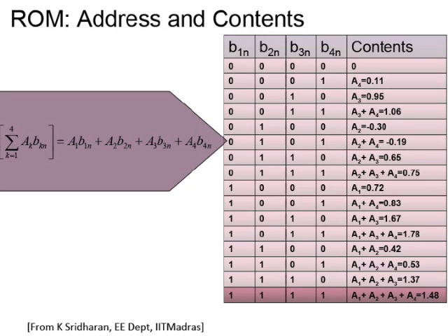So imagine you have two inverters, one connecting to the other, two back-to-back inverters, right? If you put input as 0 on one of them, the output of the first one will be 1, which will again be 0. So each will help the other. That's basically the structure of a memory cell, which is also what you have seen in the case of a latch and a flop, right? Two back-to-back inverters. Of course, in the case of a flop, you have a gated inverter, but that's basically what it is.